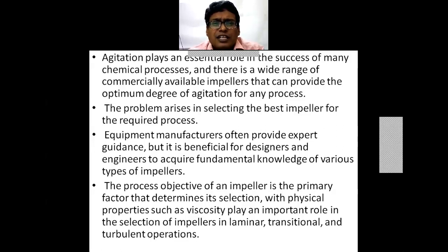A lot of agitator or impeller manufacturers are there, and chemical processes are an art also, requiring an understanding of agitation, fluid mechanics, and all your chemical engineering basics. The problem arises in selecting the best impeller for the required process. That is where the person's experience counts in all these selections.